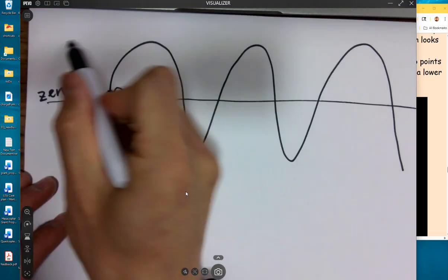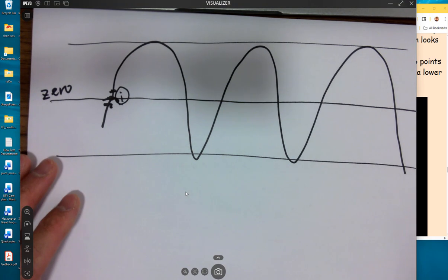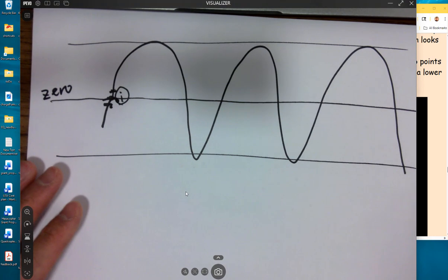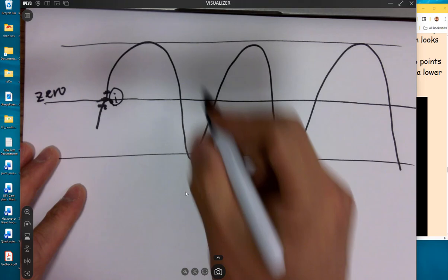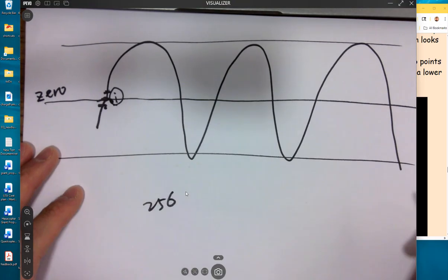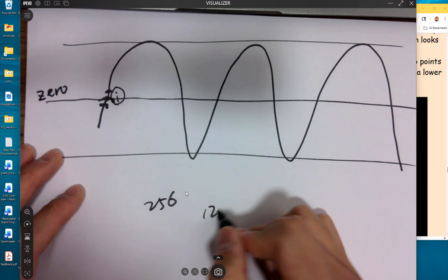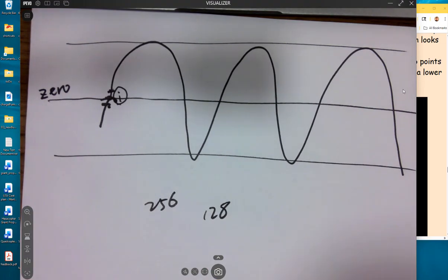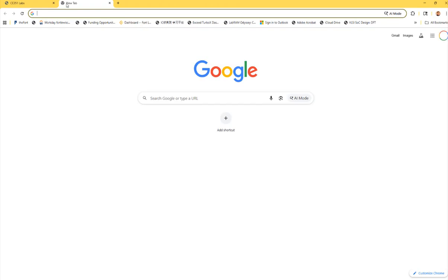But you have to find out the Y value over there. Usually for 8-bit, since we are using 8-bit precision for the ADC, if you don't turn on anything, just keep it quiet, don't whistle, and just let it sample, it should report around the middle line, because 8 bits gives you 256 as a range, so it should be set at 128 as the middle line. The reason for that is if you look at the schematic here,